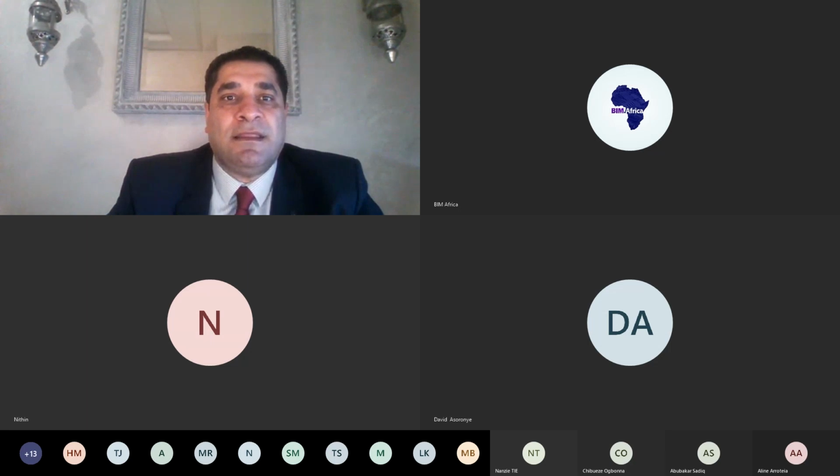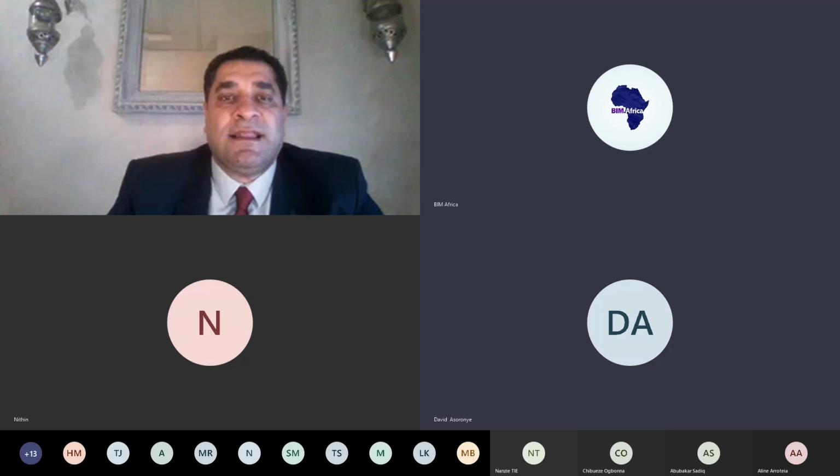Maybe here the original duration is not the same, if you subtract between this and this, because this time includes the off days, like Saturday and Sunday and other days off work. For that, Primavera must calculate the start day and end day for every item, depending on the original duration, and it will add the off days. Like Saturday, yes, we can see this.